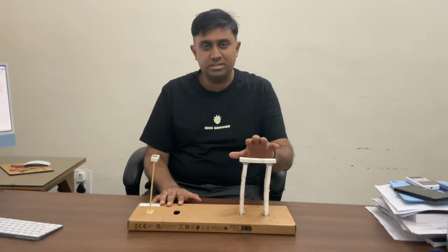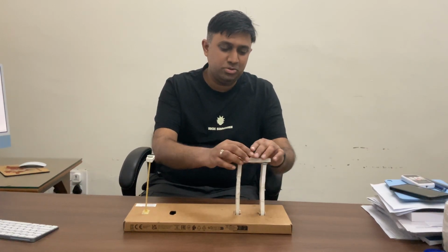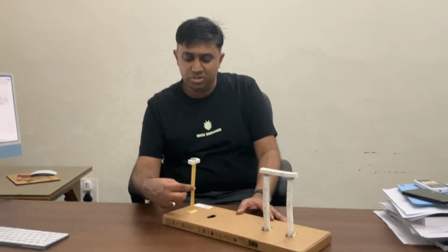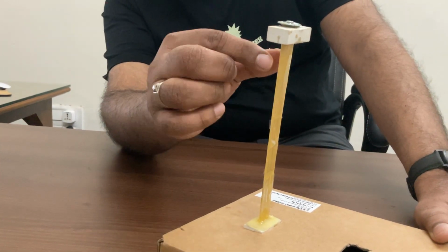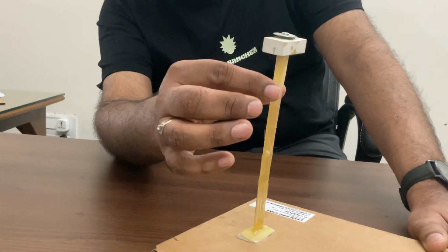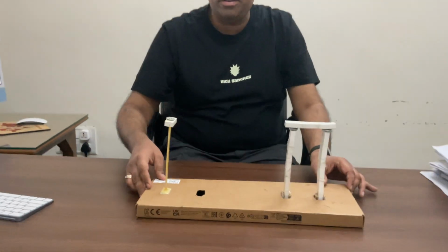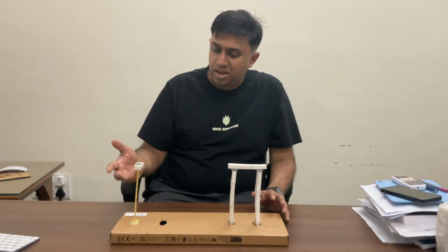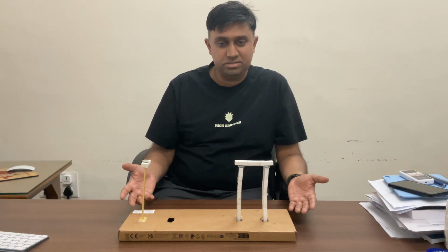And so this system, which has a higher damping ratio, I have already explained, is made up of these erasers, right? On the other hand, to construct a system with a much lesser damping ratio, we resorted to using these spaghetti sticks, right? They may not appear as distinct strands, but this whole member is made up of around 7 or 8 spaghetti sticks glued together using epoxy, and at the top we still have that eraser, right? I have worked with spaghetti sticks before, and I know that they have much more elasticity and less damping ratio, right?